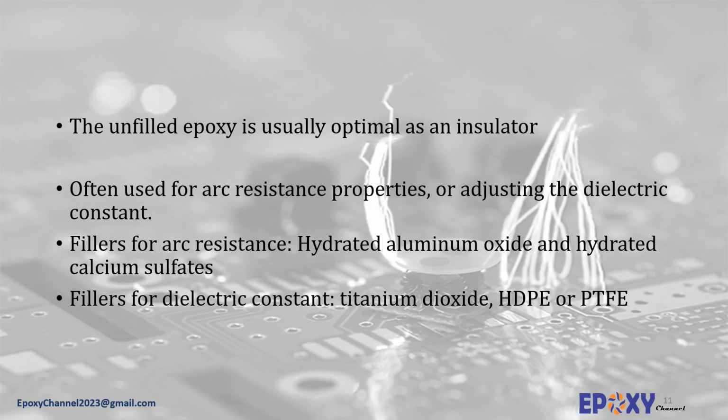Non-conductive fillers are employed with electrical-grade epoxy adhesive formulations to provide assembled components with specific electrical properties. The effect of electrical grade fillers, for example silica, on the electrical properties of the adhesive is usually marginal. Generally, fillers are not used to improve electrical resistance characteristics such as dielectric strength. The unfilled epoxy is usually optimum as an insulator.